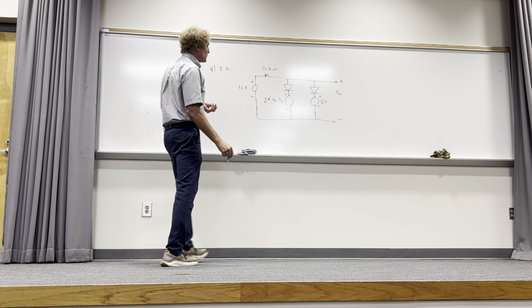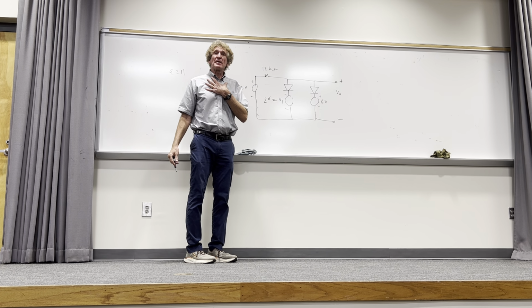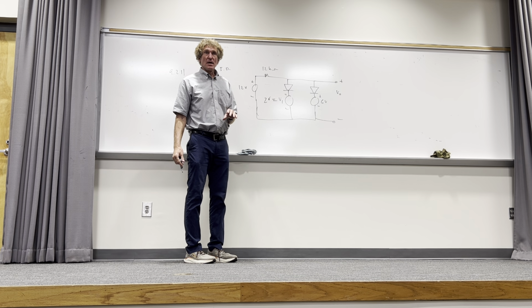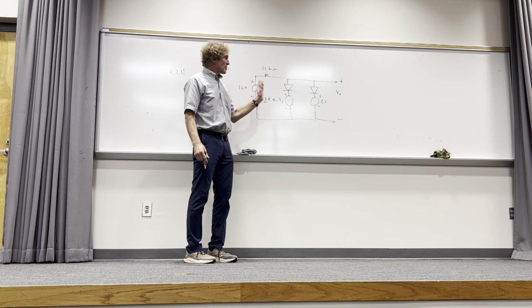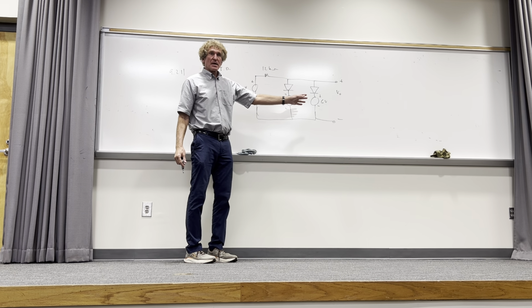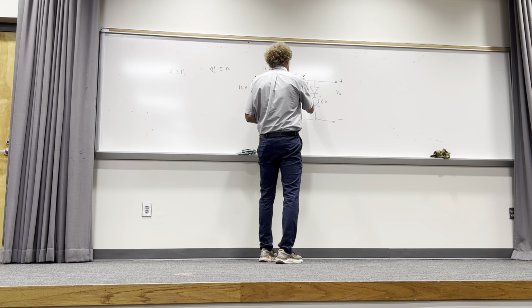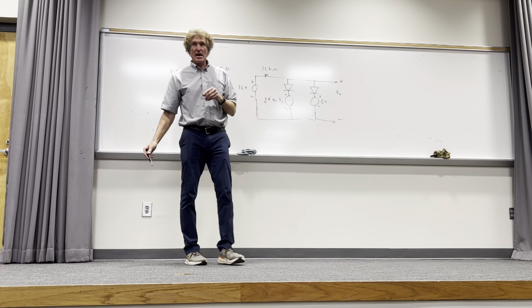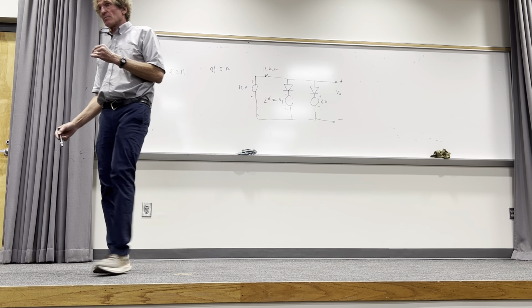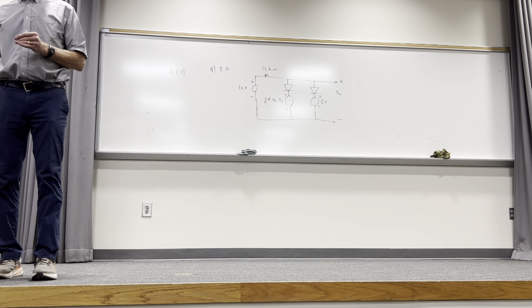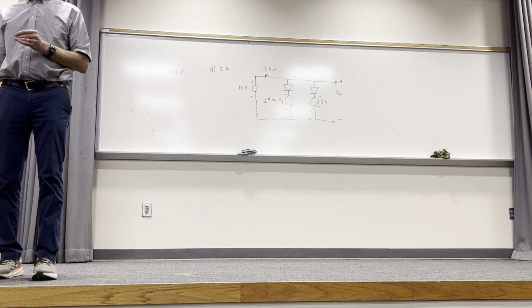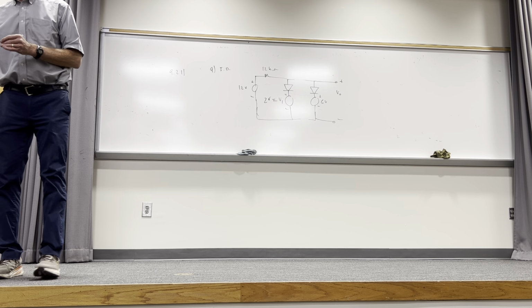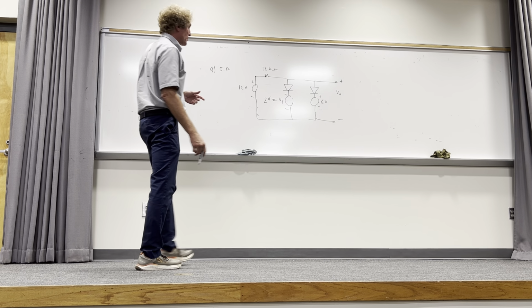All right, when you have 2 volts here, this is the way I recommend you do a problem like this. There's parallel legs here, right? Get rid of one of them in your mind. Disconnect this part. We're just going to allow this part. We want to see what happens. Y'all follow me? We're going to do this the smart way. We're going to go through and break it up into possibilities. And the possibilities in terms of diodes are they're on or they're off.